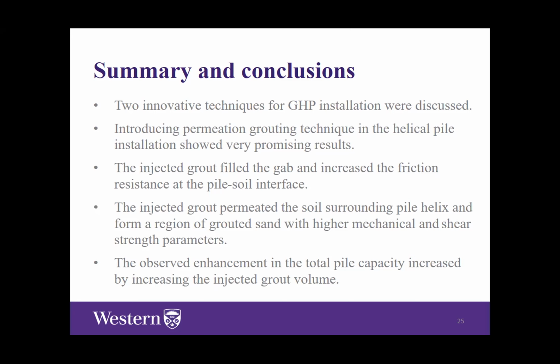So if some of the grout nozzles face more resistance due to a high percentage of fines or silt, maybe they will tend to move through the other holes. So further research is still needed here to fully understand the behavior of the permeation grouted helical pile.